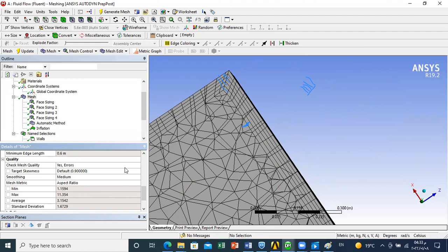What I want to tell you is that these numbers I gave you, it's good to be below them, but if you are above them, it doesn't mean that your mesh is bad. You might still have convergence. So what you can do is run and compare different meshes and see if a slightly larger aspect ratio affects your result a lot or not.